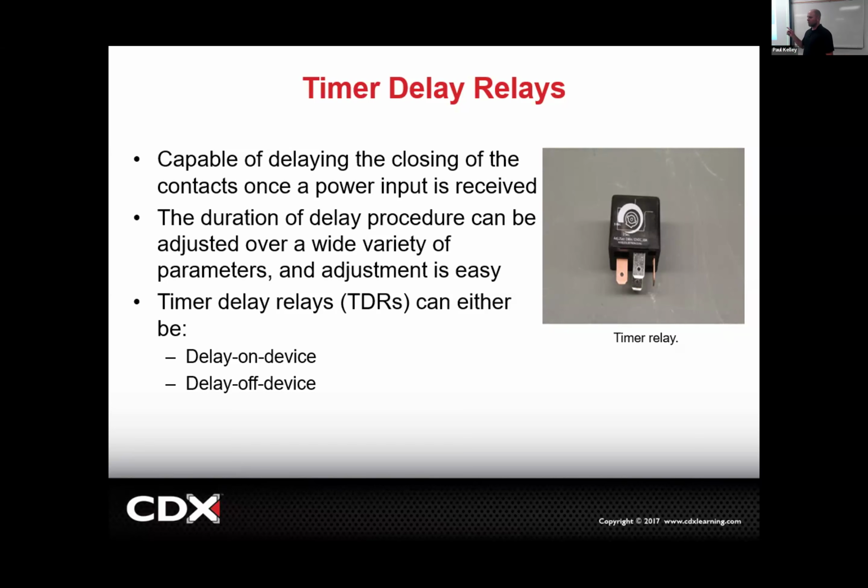They have turbo timers and relays like this where you can turn it off, take the key out, lock the car, walk inside, and this relay may stay active and continue to run the ignition and continue to run the fuel pump for a certain amount of time. And sometimes you can actually adjust the timers on these. So it's not generally factory, but I thought it's a neat thing to show you. That's the idea behind some of these turbo timers.